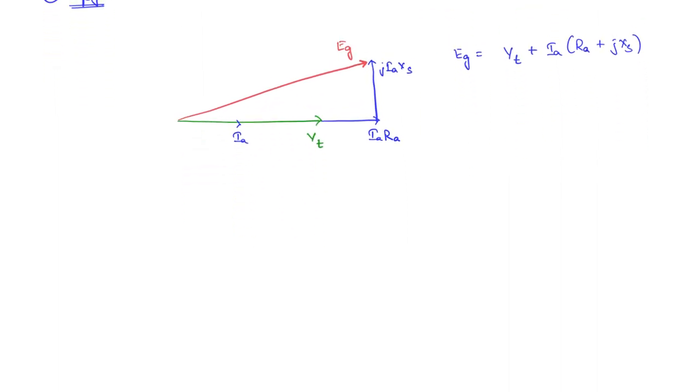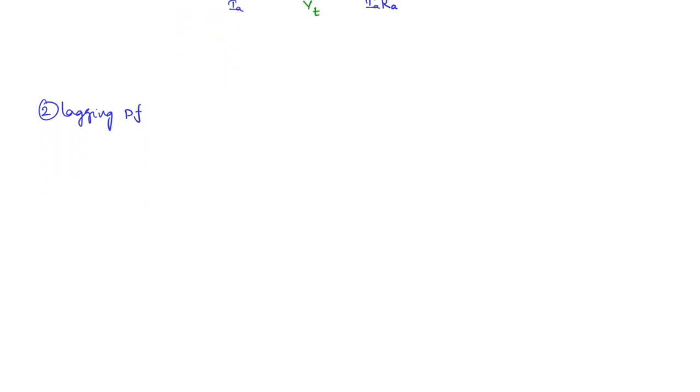Next, how do you draw the lagging power factor phasor diagram? Lagging power factor. Okay. So once again, the terminal voltage you will have VT, the reference phasor is angle 0 degrees. Now lagging PF means the current will lag the voltage, the armature current will lag the voltage. So we will take the lagging angle to be phi. Okay. Now what will be the drop IARA?